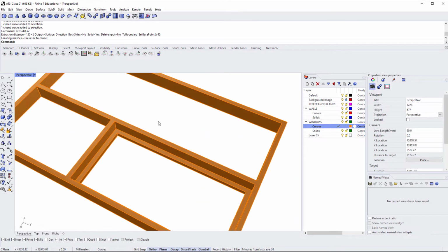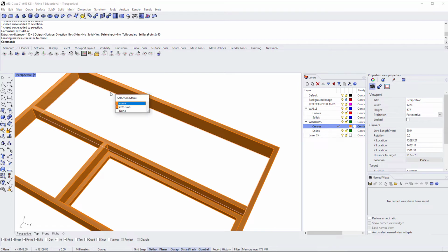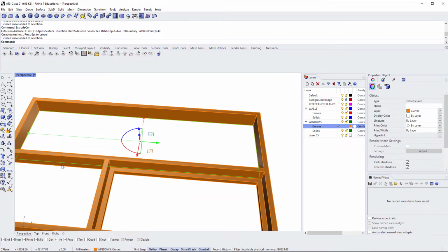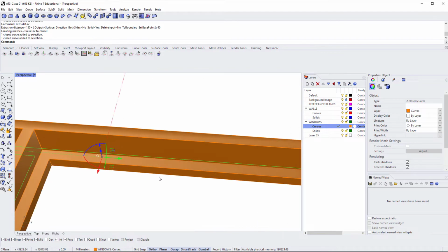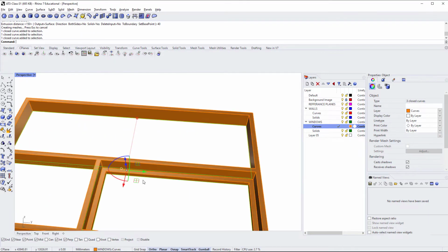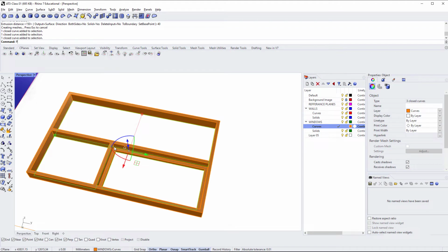Okay. Last thing to do is I'm going to select this inner curve, and this inner curve, and I'm going to use the command planar surface. So PLANARSFS. S in Rhino, SFS, is short for surface. You might not always see the full word surface, kind of like how curve is CRV for short. So with those 4 polylines selected, I'm going to select planar surface and then hit enter.